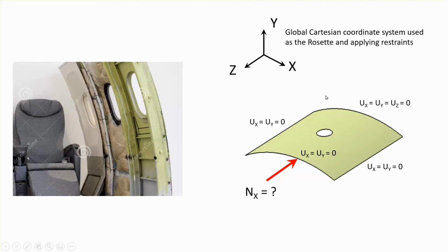Okay. And as far as the model is concerned, I talked about the edges being simply supported, and all that means, for example, the rotations are free, but as far as displacement goes, they're specified in this diagram. So we're going to be following this particular boundary condition. Now, notice, for example, on this edge, obviously, because of the load, it can compress and eventually it will buckle. That's why UZ is not given. UZ is actually not zero.